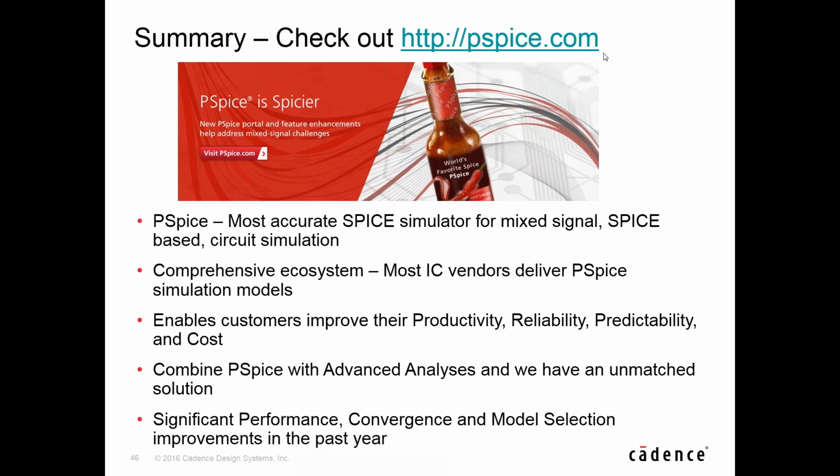For that sort of timing analysis, you can put into the model the minimum and maximum delays that you typically find in the data sheet, and then you can run a digital worst case simulation, and it will produce the worst case timing value as output.